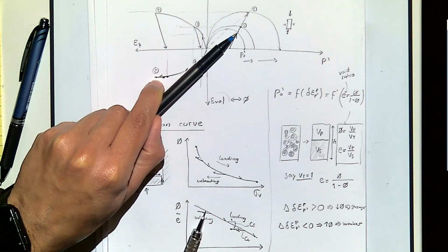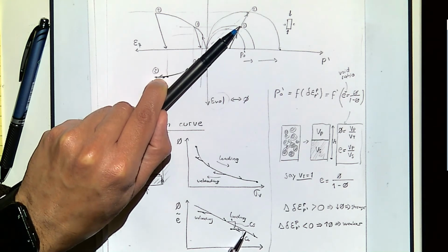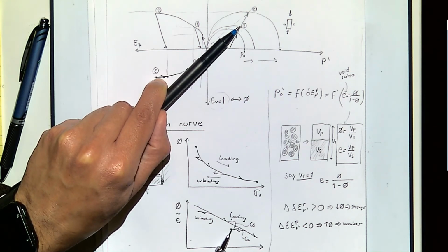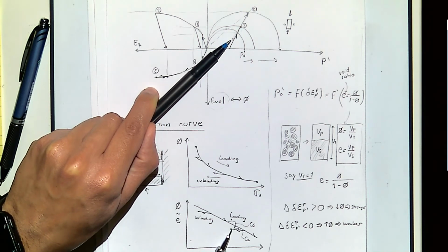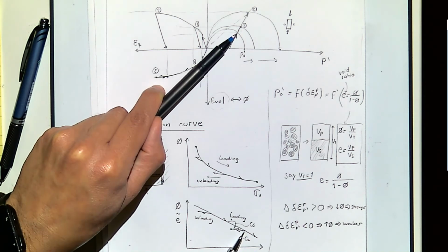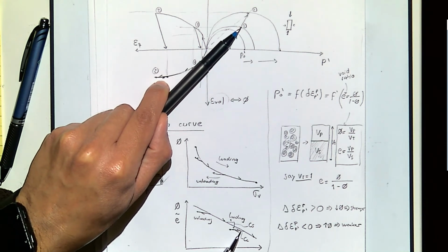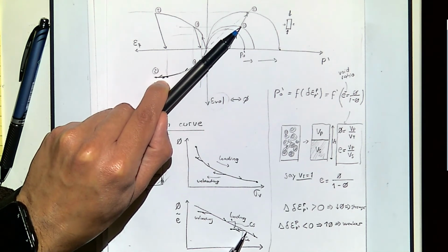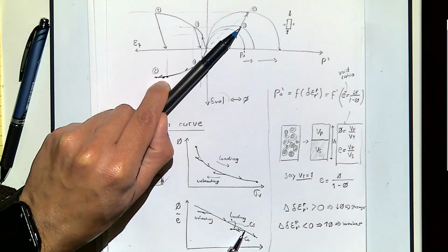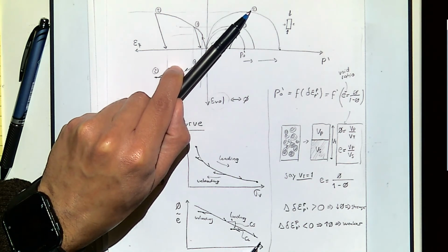And let's say that I lose all of that porosity and I get to this point. And if I unload at that point, I get back to here, unloading. If I load again, now the new point at which I'm going to have a plastic strain is not going to be this surface anymore, but it's going to be that one. So when I come back this way, and only once I get to the yield surface, I jump again onto the plastic deformation line, and I go up to there.